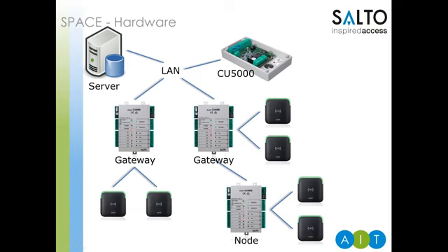This is really useful where you've got a high concentration of doors in an area. So say, for example, turnstiles. We could just provision 1 network connection, and then we could daisy chain the various nodes from a single gateway. That would then enable us to have independent control of all these turnstiles just with a single network connection. So it's saving cost in getting them installed.